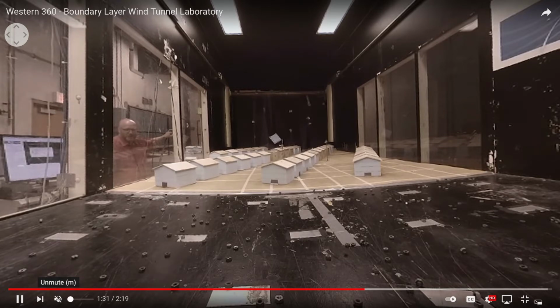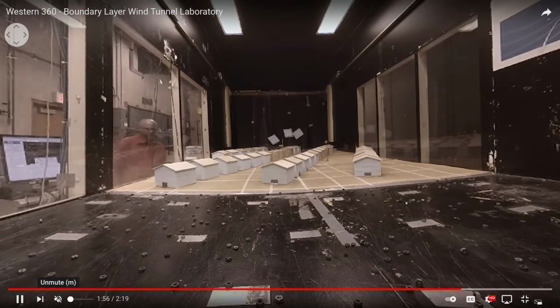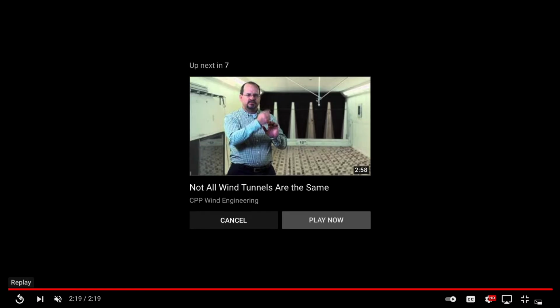It's not an unusual thing to do in design, to use scaled models to figure out how things behave, not only for things you'd imagine being in wind tunnels, like scaled airplanes, but also for buildings. One of the things is that the flow around the building relies on the other buildings around it. So if you're building the new super slim skyscrapers in New York City, which are only probably, I don't know, 60 feet by 60 feet, a fraction of a block in plan, but go up higher than all the other existing buildings, then sometimes you need to know what the wind loads are on those, and you need to take into account the buildings that are around those.